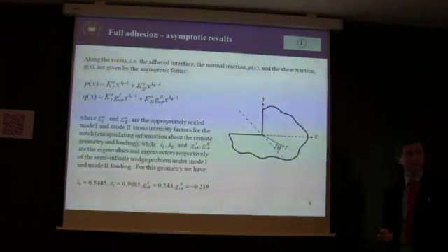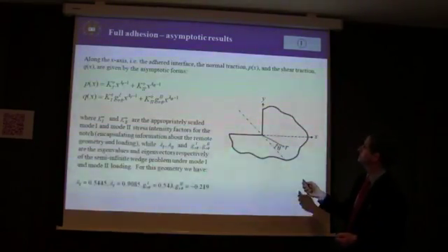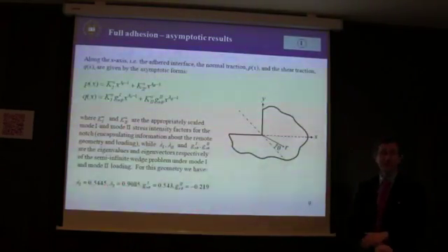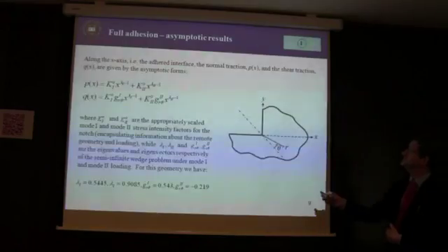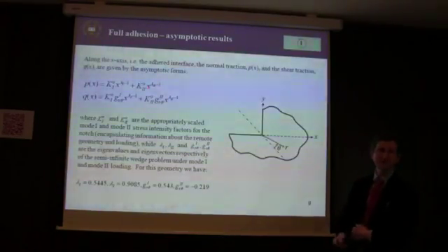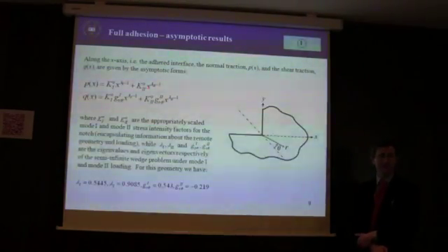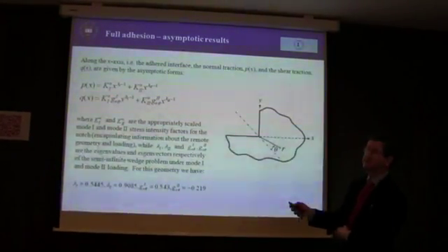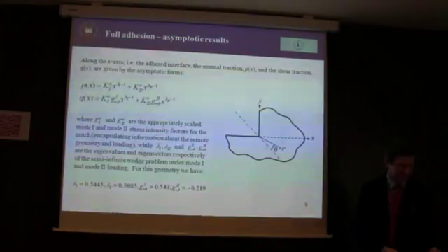Now notice that for 270 degrees, lambda 1 here is 0.544, so the lead term is just less than square root singular, whereas the mode 2 solution, lambda 2 here, is 0.91, so that this is only just power order singular. It's x to the minus 0.1 or thereabouts. So the mode 1 solution is much more strongly singular than the mode 2 solution.